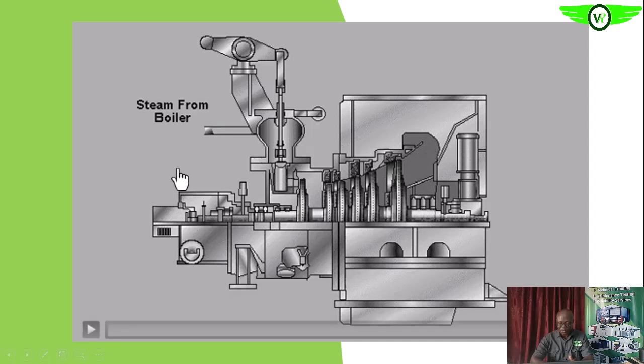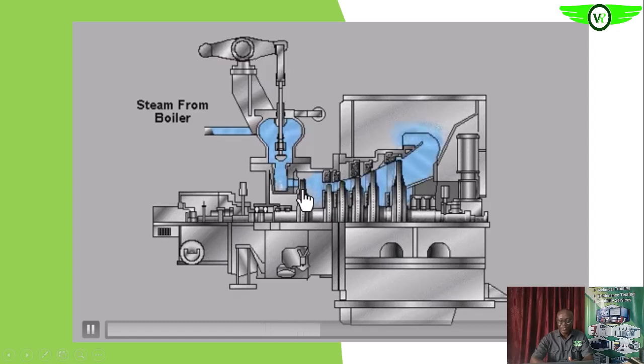So we want to see that flow of the steam through the steam turbine, and take note as it happens. So you see the steam coming into the steam chest, okay. The valve opens up, it is administered into the turbine itself, and then causes the rotation. Remember, the first stage nozzle causes the rotation of the turbine rotor. Are we getting it?